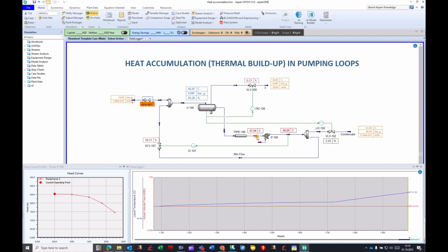It might be very quick, and it might take a few hours to reach that situation. So in general, it is wise to solve the issue by rerouting, if there is an opportunity to route the main flow line upstream of a cooler.